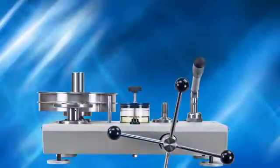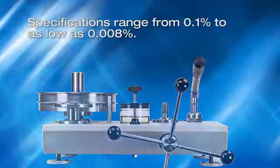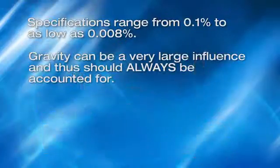Deadweight testers available on the market today have specifications from 0.1% to as low as 0.008%. As we have already mentioned, accounting for all variables and performing a full calculation of pressure allows for the best uncertainty possible. But at what point is it necessary? As we already saw, local gravity can easily result in an error that is greater than 0.1%. Thus, we need to always account for gravity in some fashion.